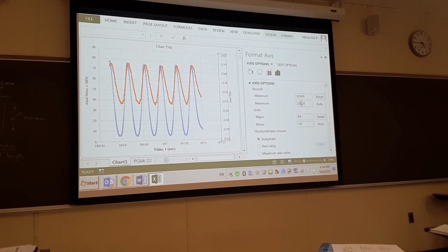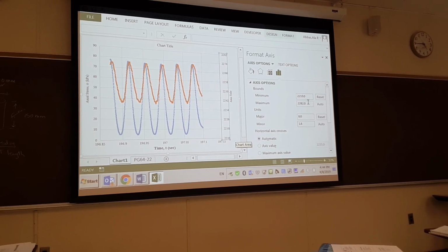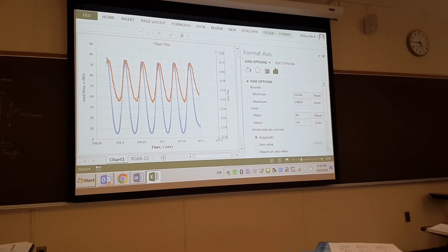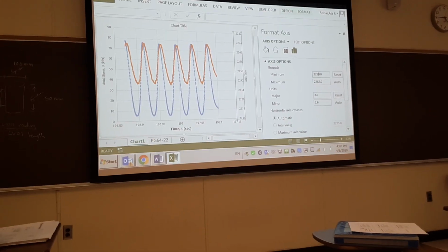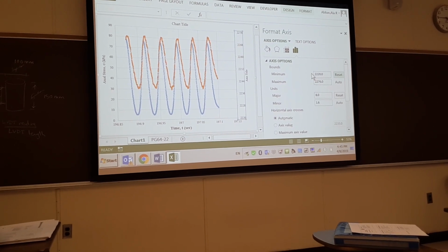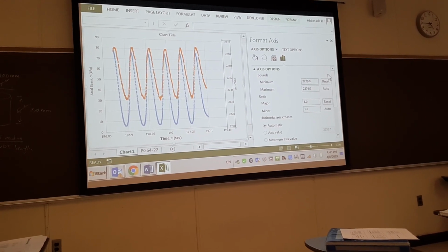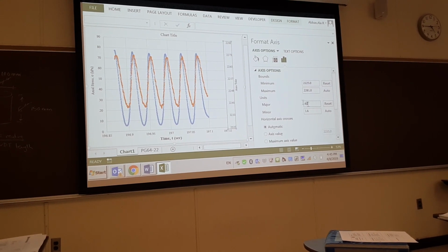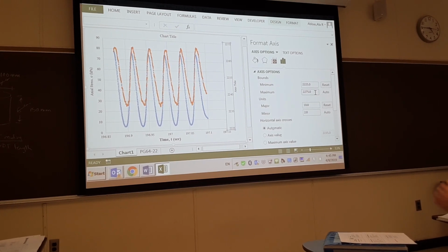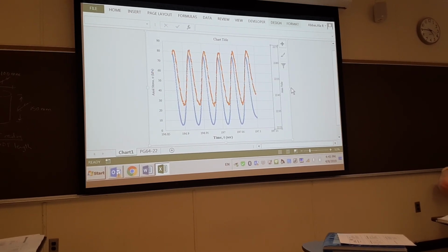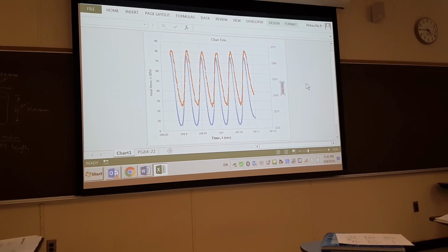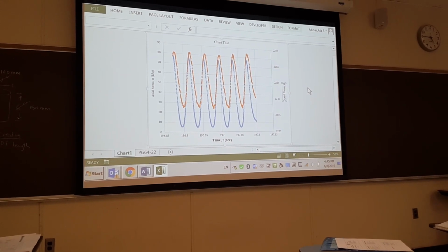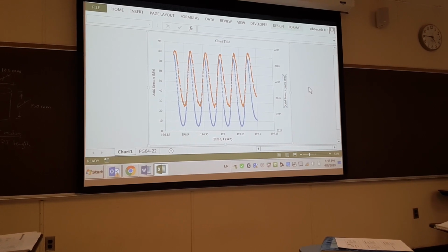So you can see in here, we're losing a little bit of the resolution. I would rather make it a little bit better. So in here I'll do this 20, 25. Again, you got the point, but in here I just want to change this to axial strain. And this is epsilon, and we agreed that this is microstrain or micromillimeter per millimeter.